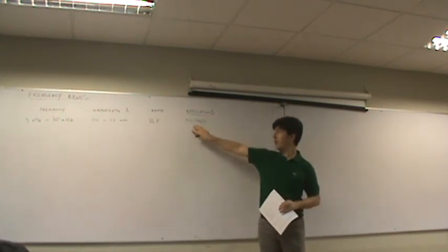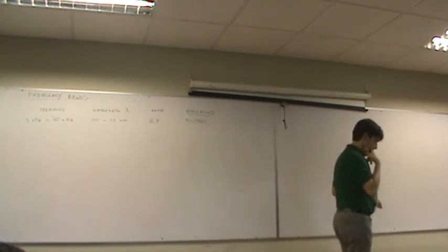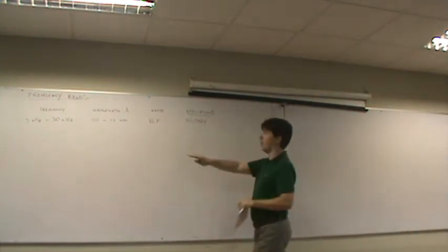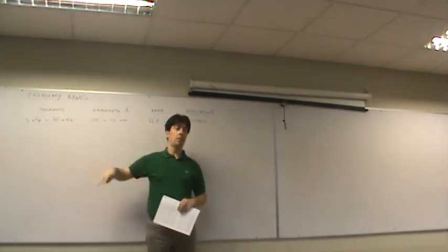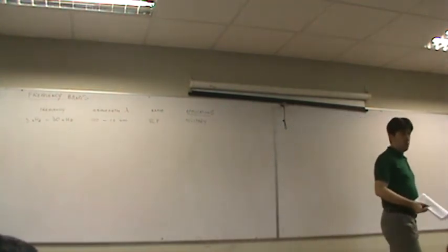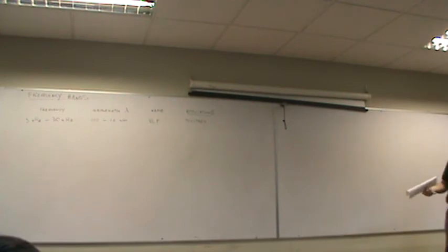Those very low frequencies can penetrate the surface of the sea for several meters. You can imagine what they're used for: to communicate with military submarines. At very low speed, because you have a very, very narrow bandwidth, so your bit rate must be very low. But good enough to send some signals.